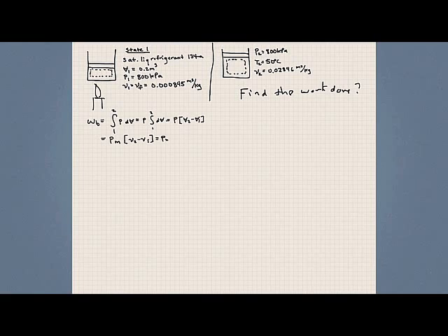Well, we know the specific volume at state 2, and we know the specific volume at state 1 is the saturated liquid state of this particular fluid. So now we have the values that we need to solve this problem. What we are lacking is the mass. That's the only unknown. Well, let's solve for that, and let's do that over here.